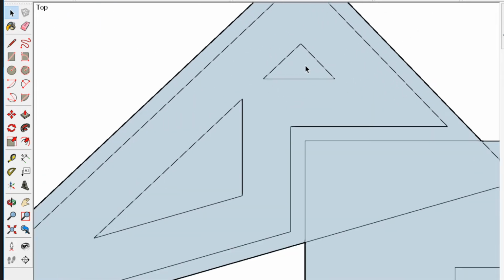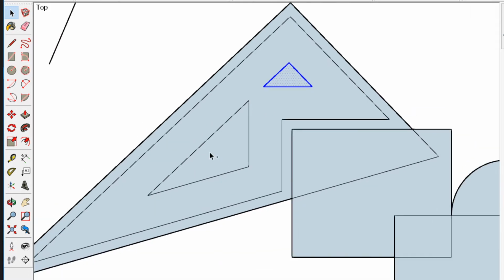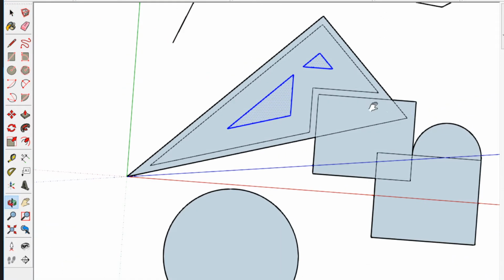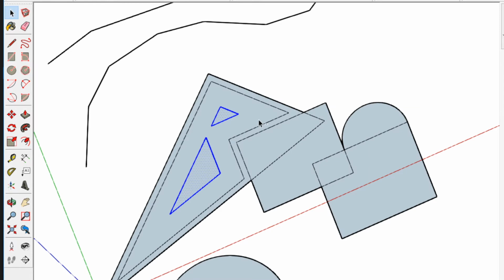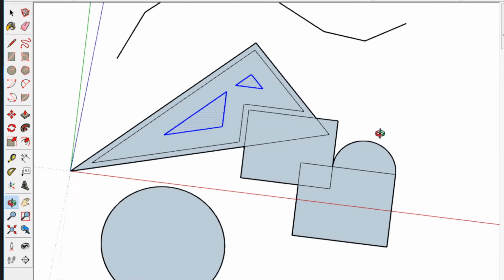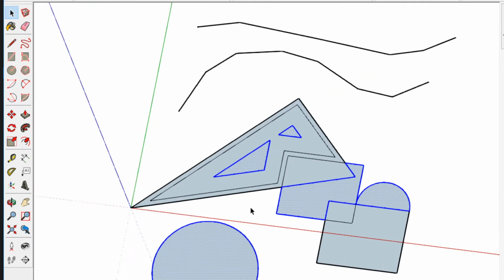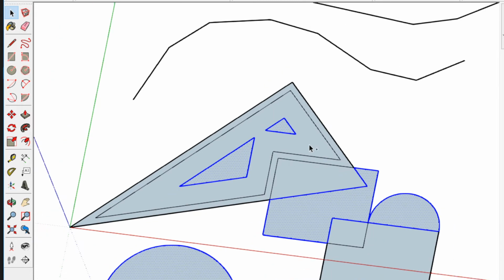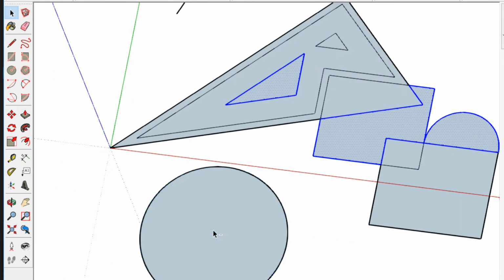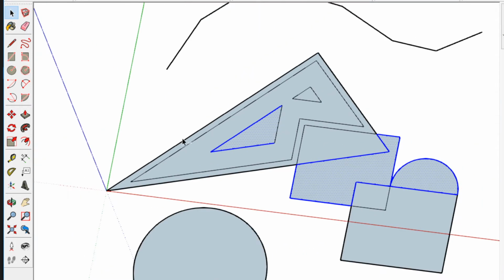Say for example, double click, hold down Control, you can see the plus sign, double click, and I am also pressing Shift for panning with my scroll wheel while holding down Control. Double click, double click, double click. To deselect, Control Shift, double click, double click. Or if you want to remove just an edge, click once. If you want to deselect everything, triple click.